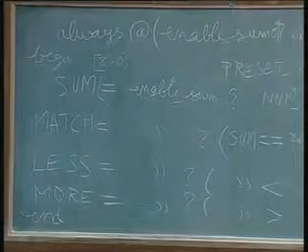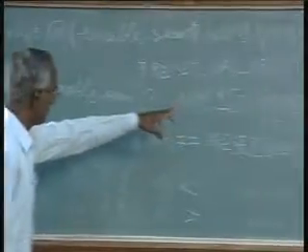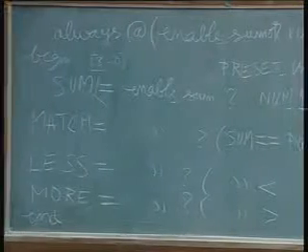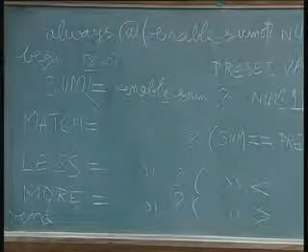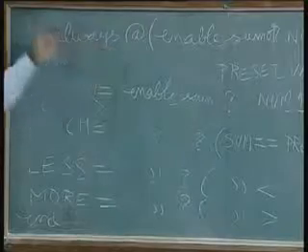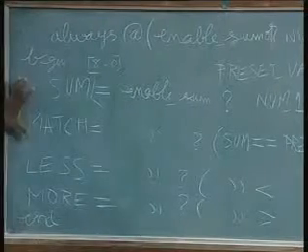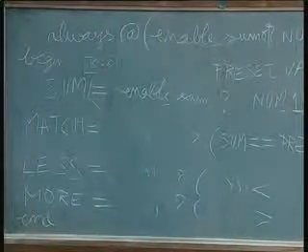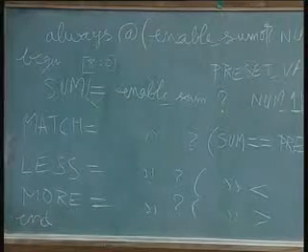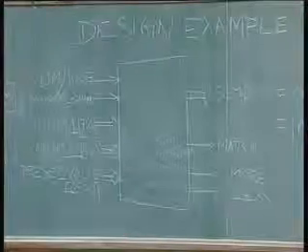Right. To summarize, what we have done so far is we have used multi-precision in the place of single precision in the case of the full adder seen earlier. And next we have used precisely the same comparators. We have also combined an always block, and the same thing can be made by putting assign statements. But when you put assign statements, it keeps on churning continuously, because it is precisely the gate that is going to be mapped onto the device. So it will be working all the time. If a circuit is working, it consumes more power. So the always block is preferable because this will work only when any change is encountered there.